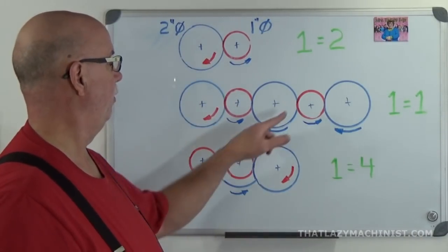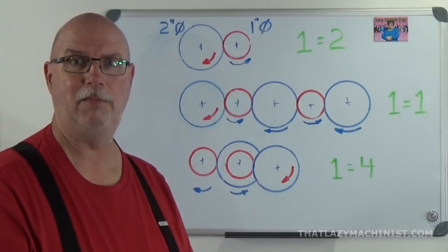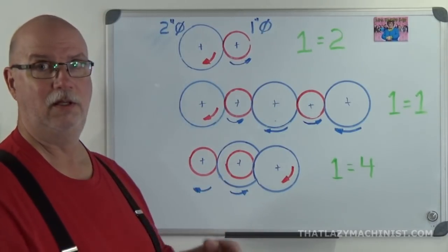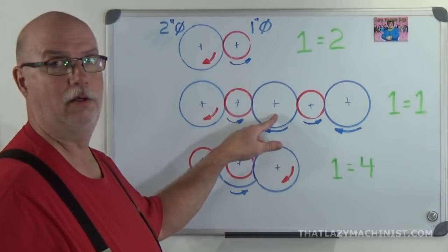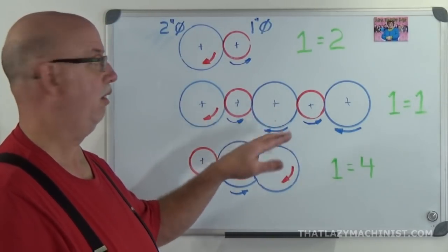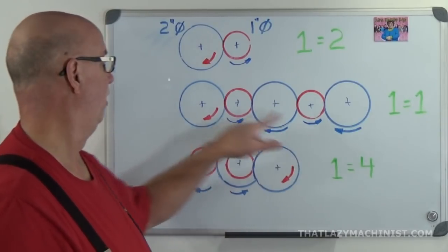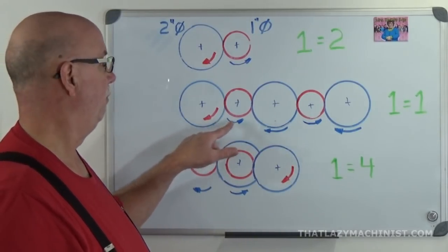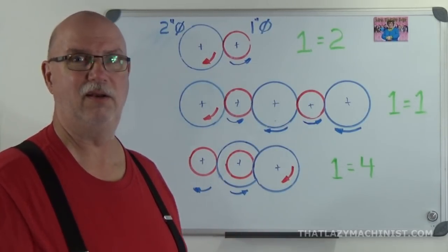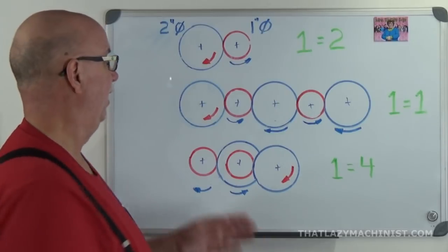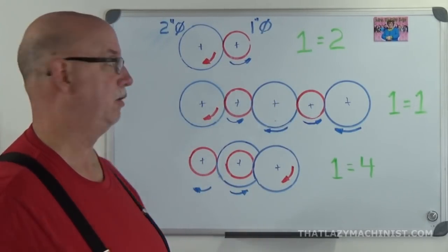Push one step further. This large gear turns this gear. I come back to my ratio, which is 2 turns to 1. So 2 turns of the red one to 1 turn of the blue. Or we can just cut those out and say 2 turns of this red one for 1 turn of the blue. Because these 2 intermediate gears, we call them idlers. They serve no purpose except for gapping the space between the 2 end gears.